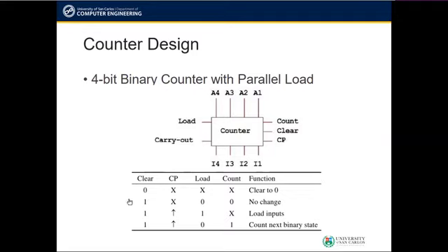We can see here next that when load input is 0 and count input is 0, there is no change in the count output, since you are not triggering the load or the count input pins. Both pins need a 1 input to be triggered.